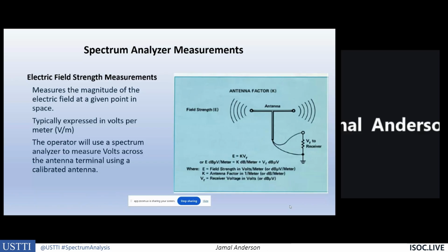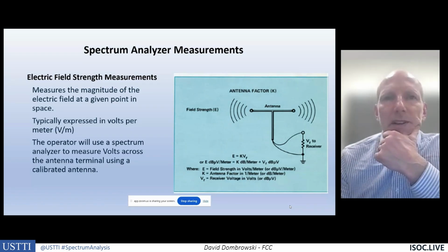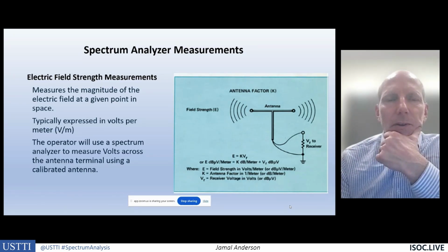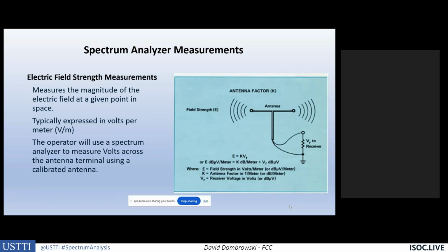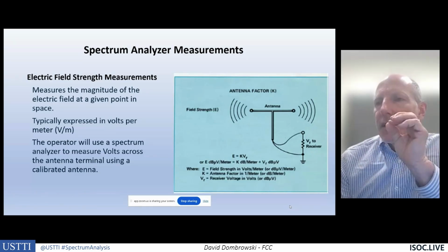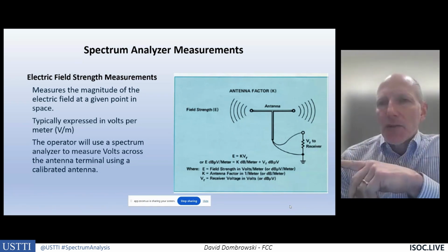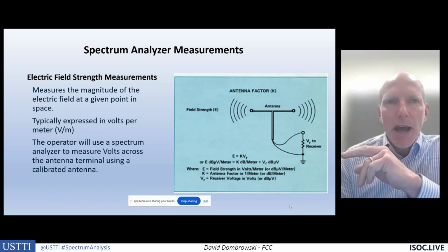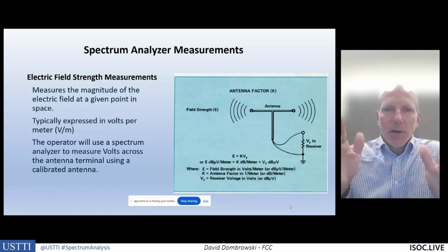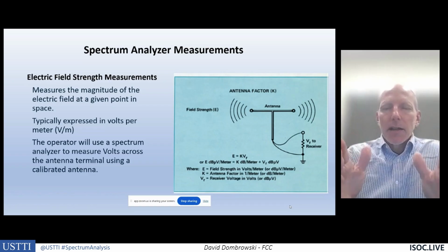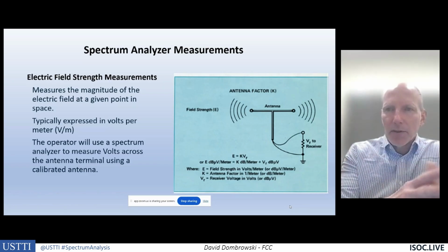Great, thank you. And then what is the importance of sweep time to determine RBW? All right, so we're talking sweep. What is the importance of sweep time to determine the resolution bandwidth? Okay, so in a fast Fourier transform, the sweep, or the processing time, was impacted by the span, how many frequencies we're looking at and processing at once, not so much by the resolution bandwidth filter.